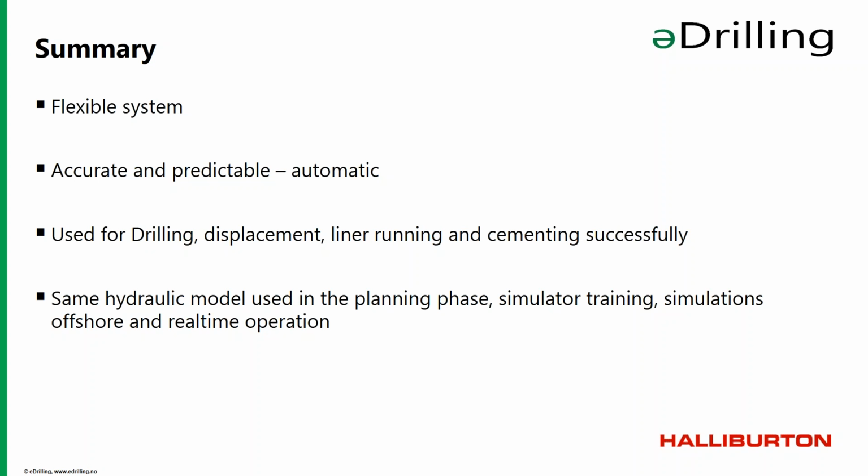So, can the hydraulic model perform simulations for multi-phase fluids like foam in MPD operations? That's a good question. The model is basically a multi-phase model. But when it comes to foam, we haven't been doing that many simulations on that. We have done a lot of cementing with foam cement, but what we often do then is that we simulate that the foam is stable and not changing too much. And that is something we have been looking into, using nitrogen in the model.